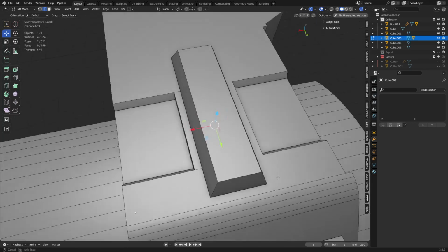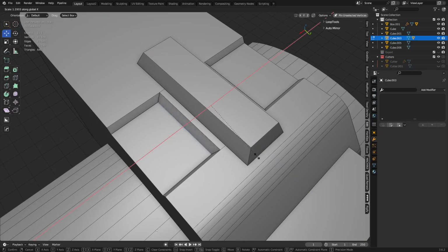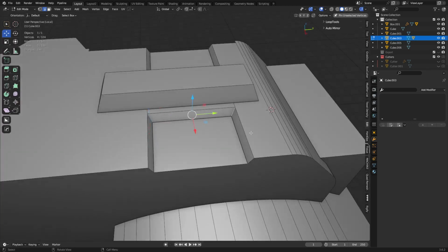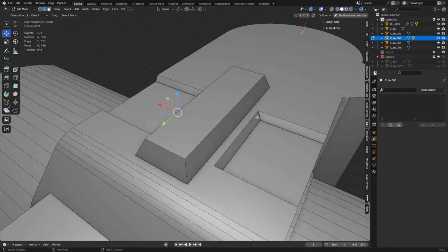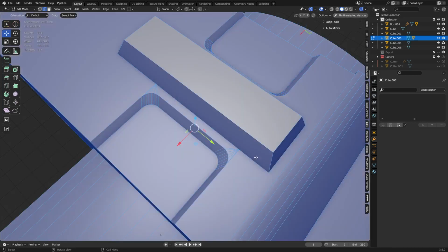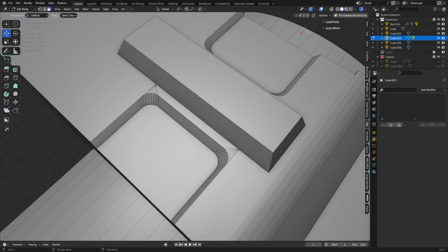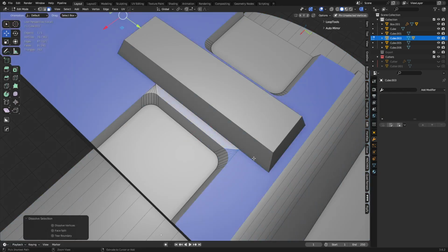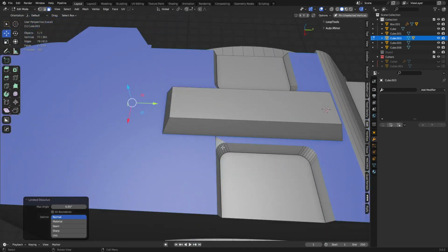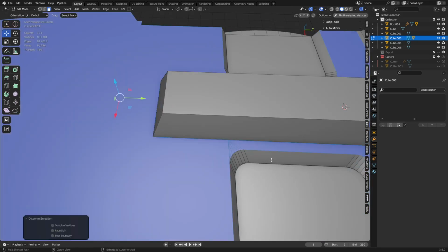And these two here, we can select and we can go ahead and push them out like that. If we wanted to try beveling these later, we could do that. Probably be better to bevel all these at the same time. We could do that number. And also cursor select an area if you need to, and then just control X on that or X limit dissolve on that, as opposed to doing the whole geometry. Sometimes that works out much better.